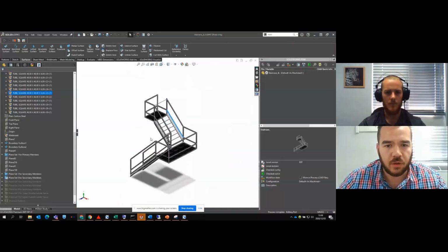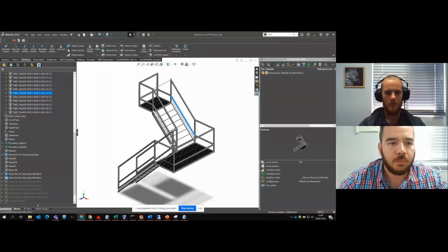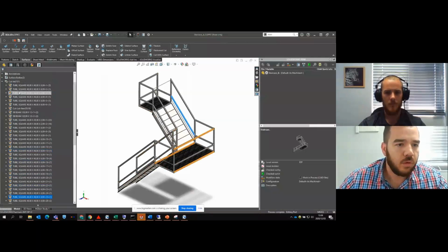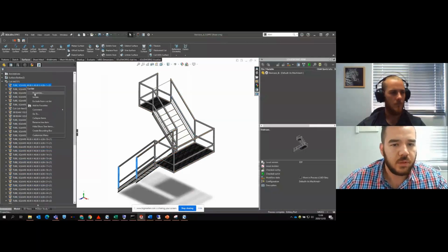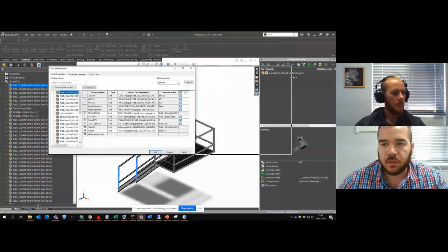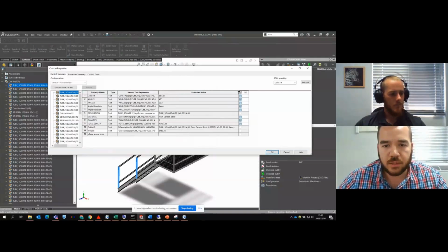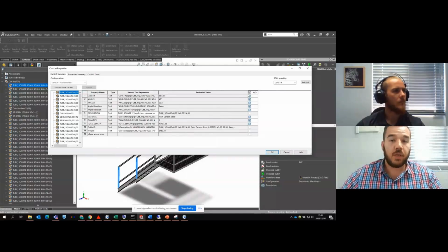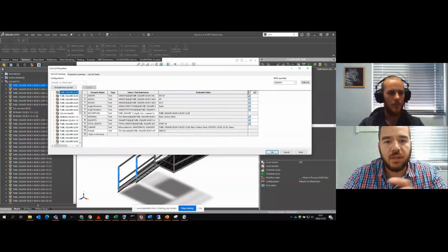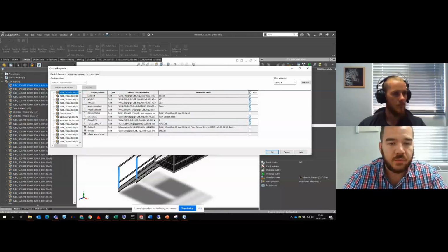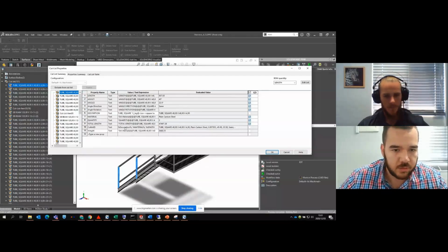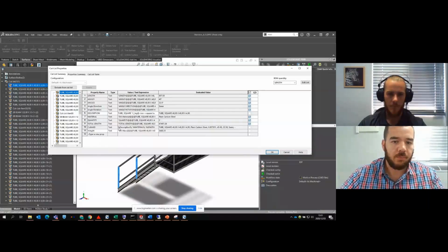So if I have an example, like a staircase with weldment properties, and I've got all of my different Cutlist items, most of the clients that know a bit of SolidWorks and SolidWorks PDM know that you can link the variables. So it's actually a very nice feature to have. For example, this Cutlist that you showed, with this percentage sign, it's actually just a placeholder.